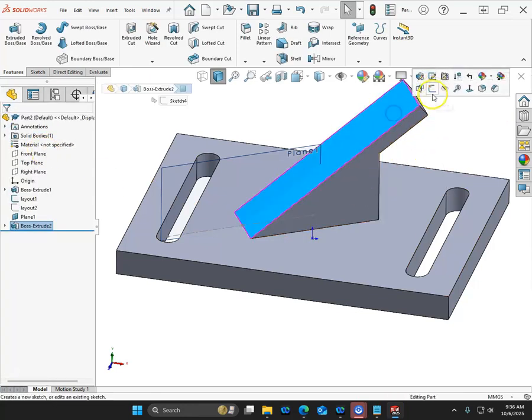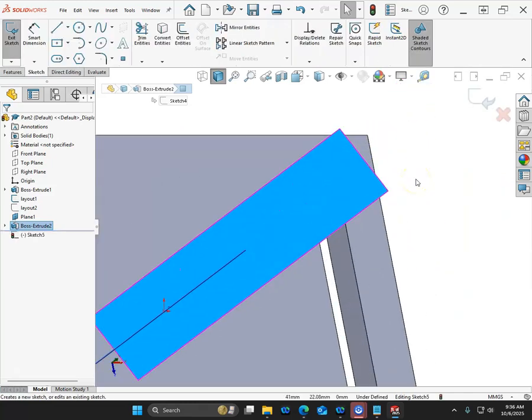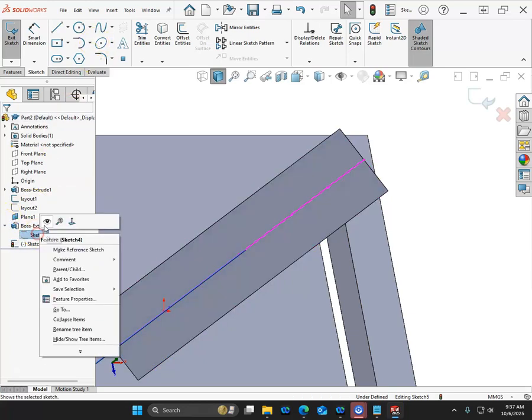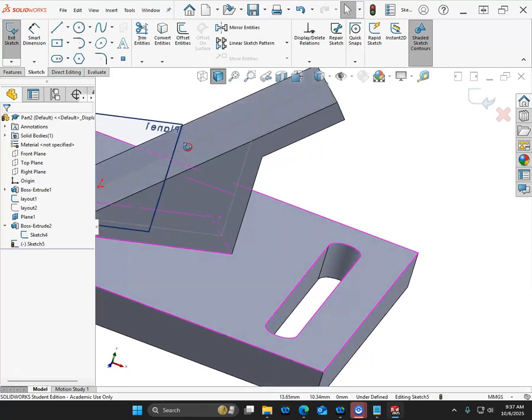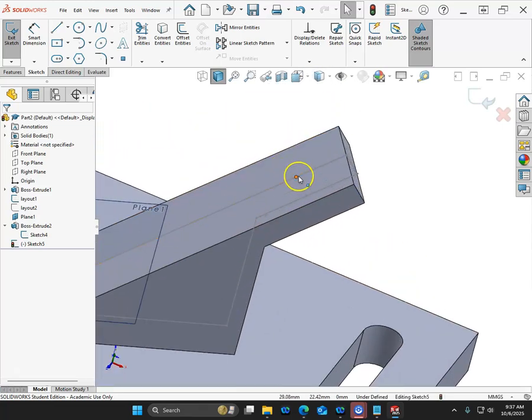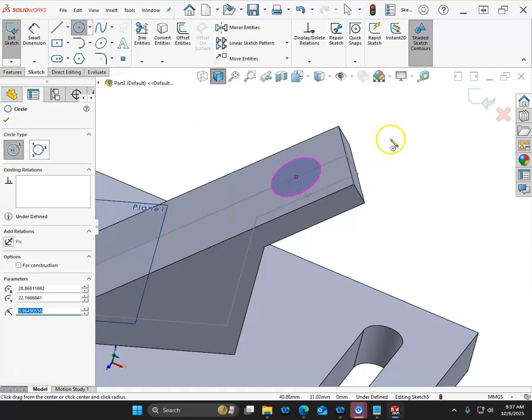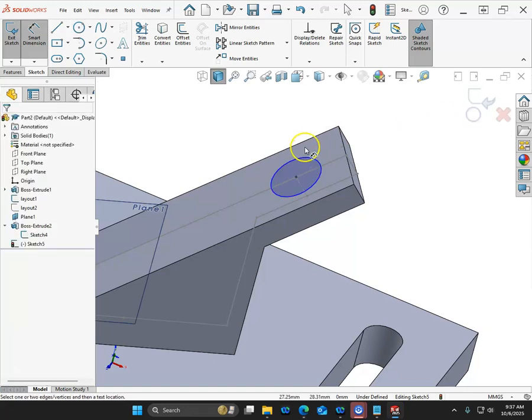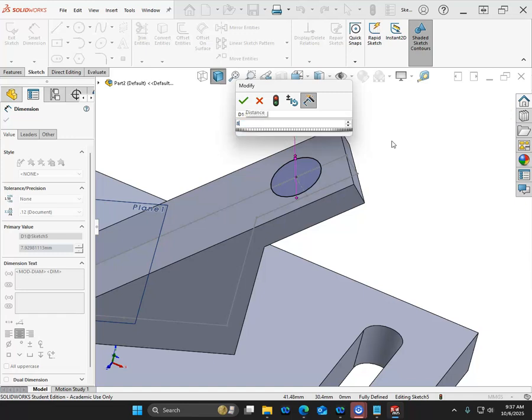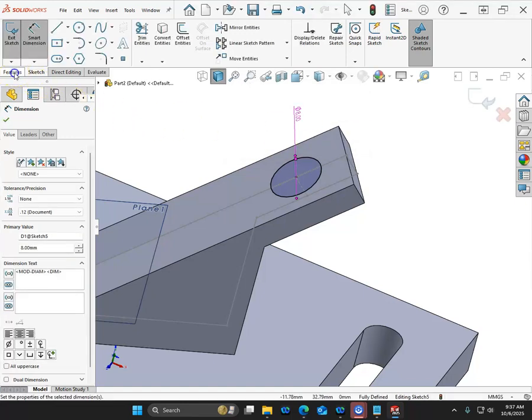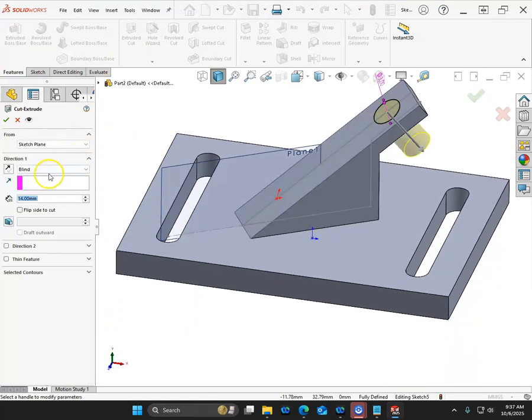And then we can open up the sketch. And I am a little hesitant to put the radiuses on, but let's go ahead and see what it does. Now if I show this sketch, and then rotate over for the isometric, that point is lying in the sketch plane, so I can use it to add a relation and then put in the dimension, and we have a diameter of 8. And then we're going to extrude cut up to next.